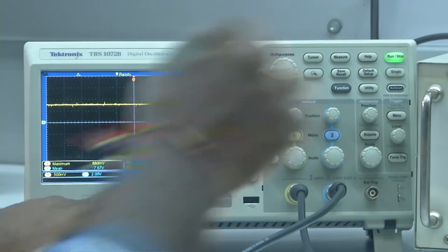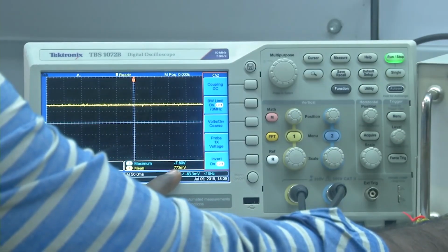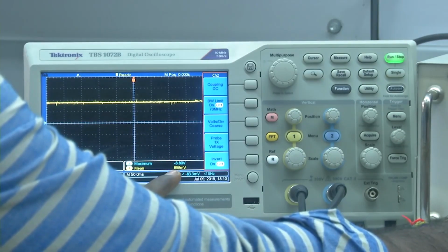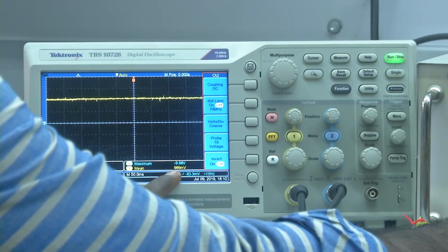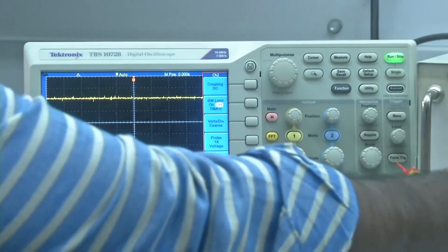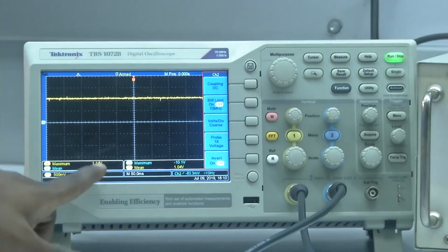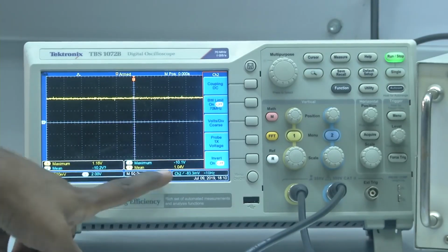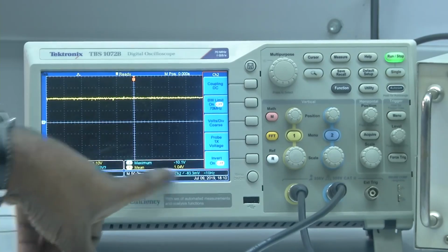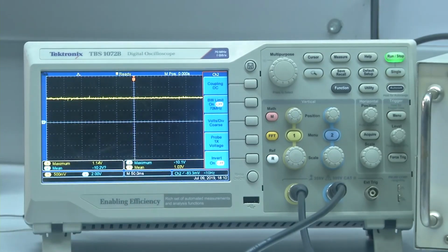So now if you observe, I am giving 1 volt. Let's see what I get when I give an input of 1 volt, right. So I have provided an input of 1.04, I am getting an output of 10.2. So from this it is clearly seen that it has a gain which is close to 10. 10 point something, but very close to 10, and the magnitudes are the same, but there is a phase difference.